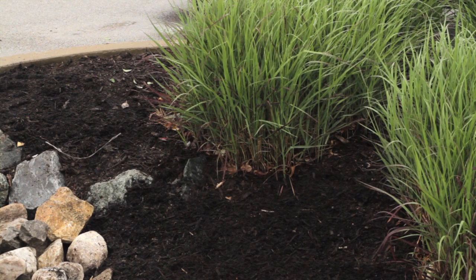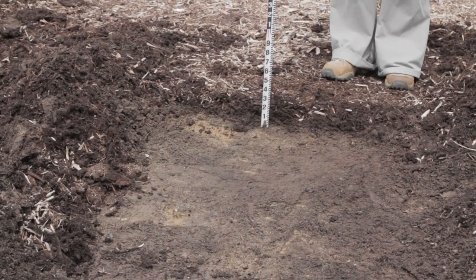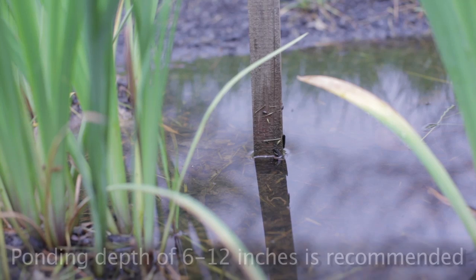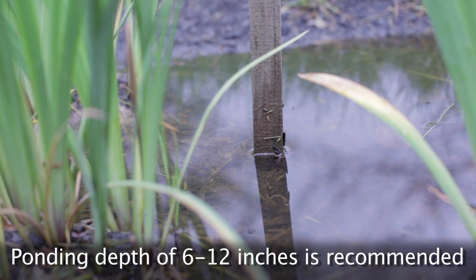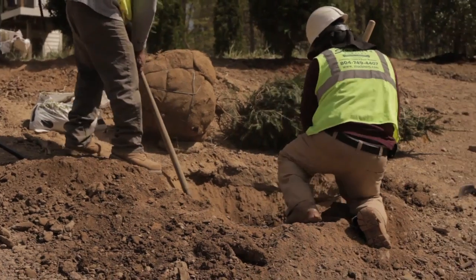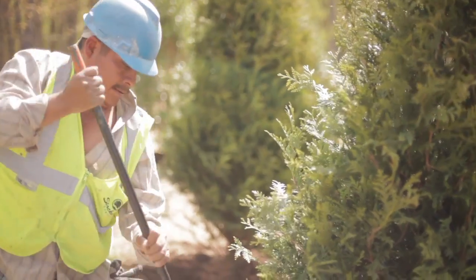Ground cover typically consists of mulch, turf, or stone. It is important to inspect the thickness of the mulch or stone layer. A common problem is too much mulch, which can displace ponding volume and change flow paths. Make sure the ponding depth is at the specified elevation, usually 6 to 12 inches. Plant trees away from underdrains and stake trees if a sand media is used.